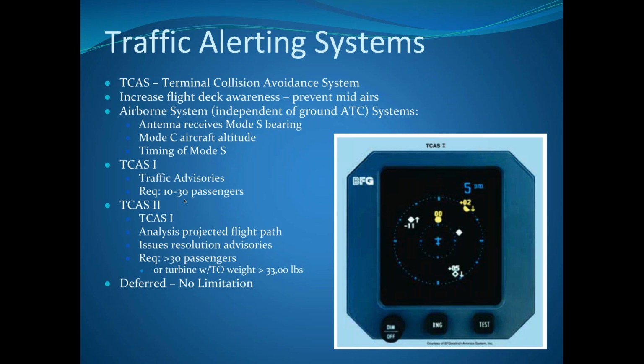So if it gets deferred, meaning that there's an MEL on the TCAS, that means no limitation. Except for you can't fly in RVSM airspace if your TCAS is deferred, I thought. I'll have to check on that. That might be needing an update.